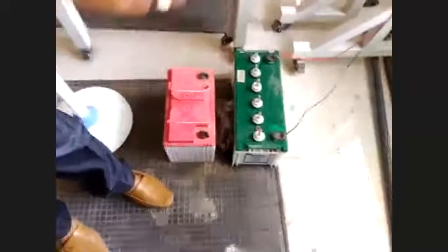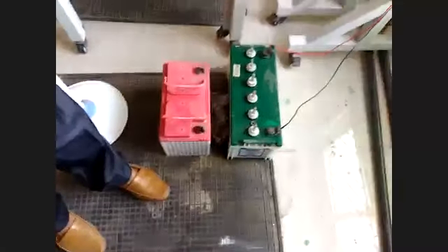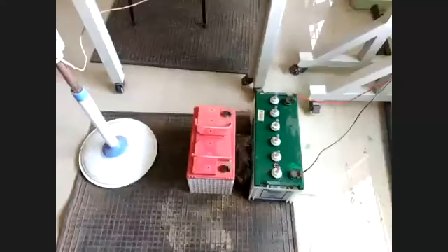It is somewhere between 70% and 80%, so better to choose the lesser: 70% depth of discharge of the battery capacity. Now you must calculate the minimum ampere hour of the battery. In this regard, one general common formula is there.